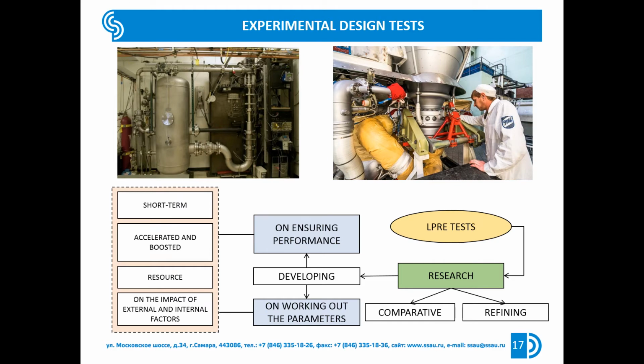For multiple-use liquid propellant rocket engines, the scope of tests for testing and verification of reliable operation of ignition systems and automatics designed for multiple actuation is increased. Methods of control of technical condition of LPRE after firing starts, cleaning of LPRE from residual fuel components, and preparation for long-term storage are also practiced. Once the required strength characteristics of the elements have been obtained, the developmental firing test phase of the full-size liquid propellant rocket engine begins. Tests are conducted with a gradual increase in thrust level and operating time.